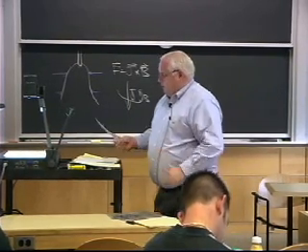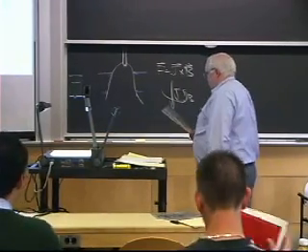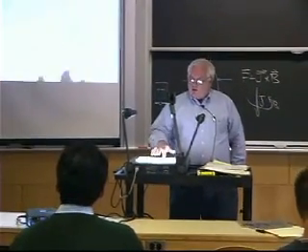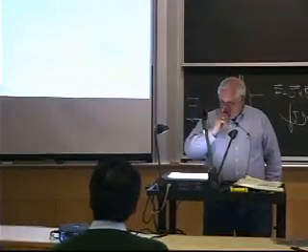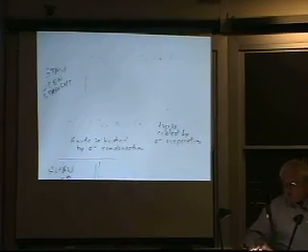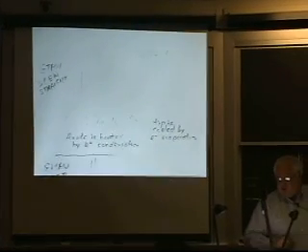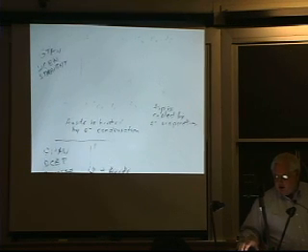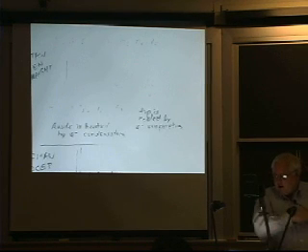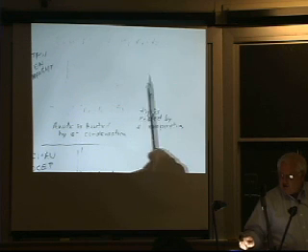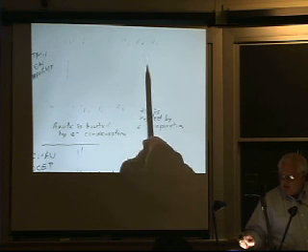Have. Last time we were talking about arcs, and I pointed out that only 1/3 of the heat is transferred to the cathode, and about 2/3 of the heat is transferred to the anode. And we talked about why you'd use straight polarity in gas tungsten arc welding and reverse polarity in gas metal arc welding. I mentioned that Professor Savage had actually measured with a pyrometer moving up a tungsten electrode and found